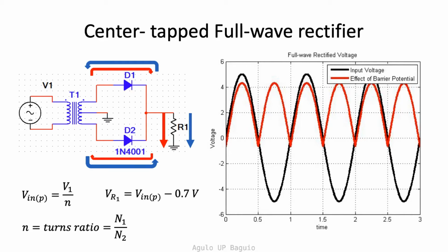At the secondary coil, if the turns ratio is 220:12, then the voltage across the secondary coil is 12 volts, and the frequency is still 60 Hz. In a transformer, this is an RMS voltage as well. The peak voltage is 17 volts.